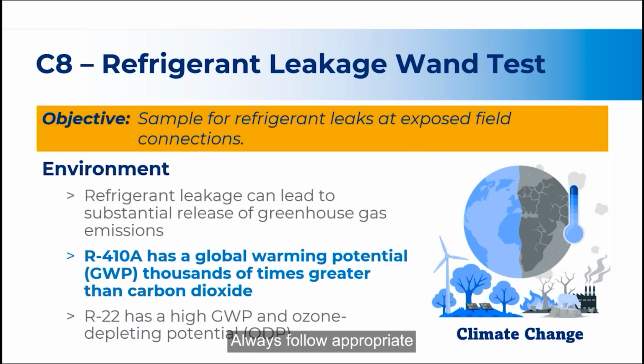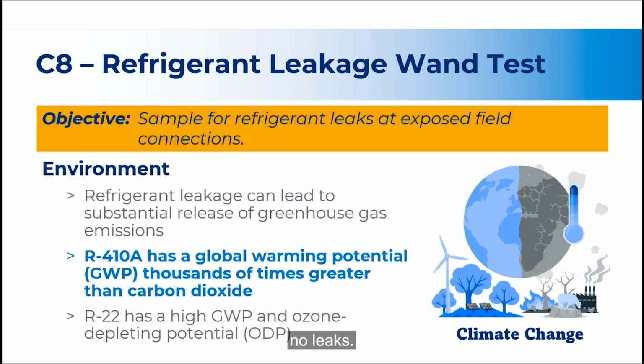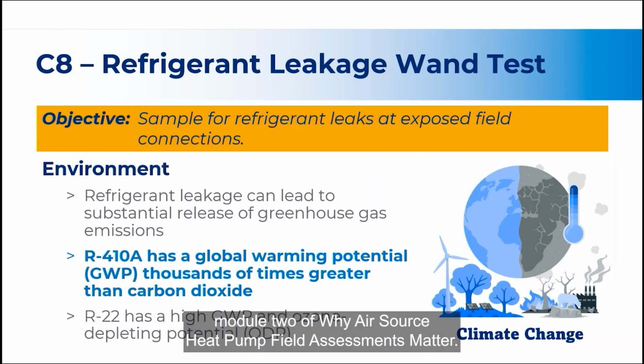Always follow appropriate procedures, pressure tests, and evacuate the lines before charging a new system with refrigerant to ensure no leaks. This concludes Module 2 of Why Air Source Heat Pump Field Assessments Matter.